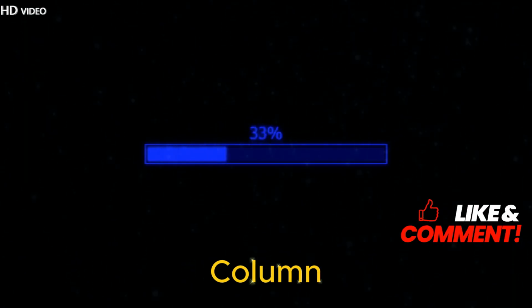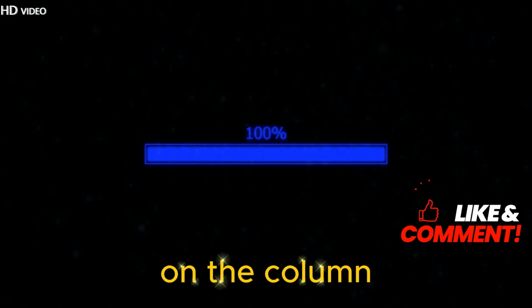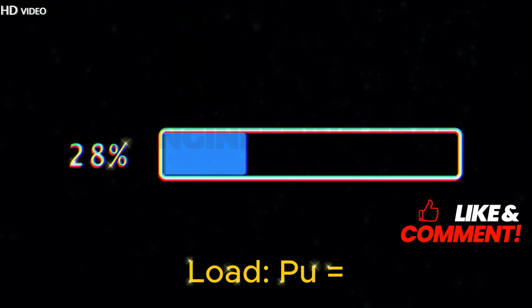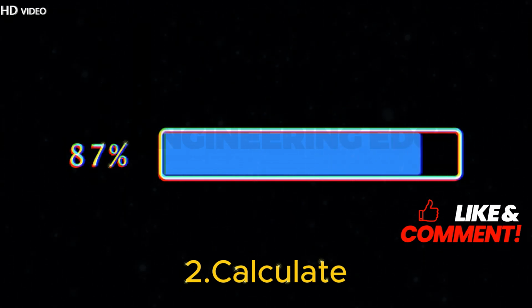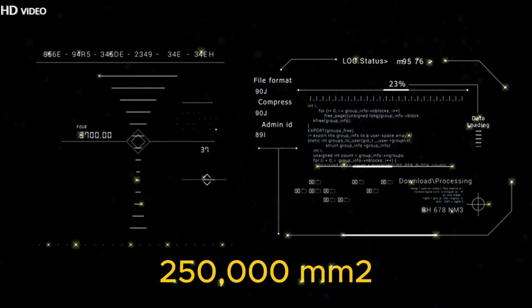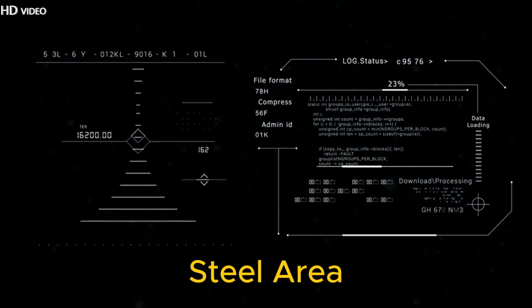Section 2. Column design. Load on the column W equals 1,500 kilonewtons. 1. Calculate the factored load. Pu equals 1.50 x 1,500 equals 2,250 kilonewtons. 2. Calculate gross area of column. Ag equals 500 by 500 equals 250,000 square millimeters.